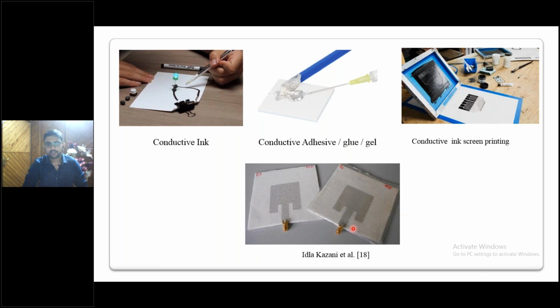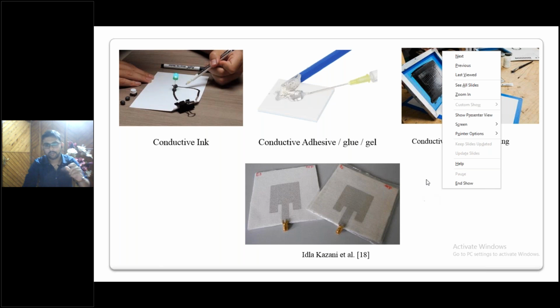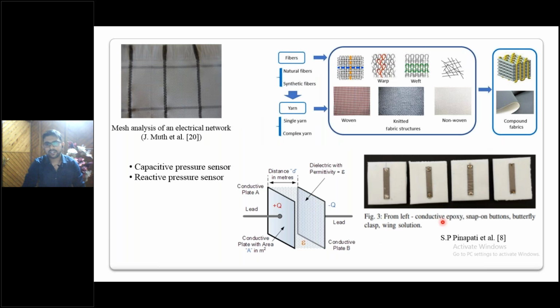Then this point is very important, because as of now it looks as if it is a very rigid device. This golden-colored SMA connector is rigid. It's actually rigid, but our target is to make it flexible. So we can use conductive epoxy. It's almost like a conductive adhesive, but essentially it doesn't always work. Sometimes it works, sometimes it won't.